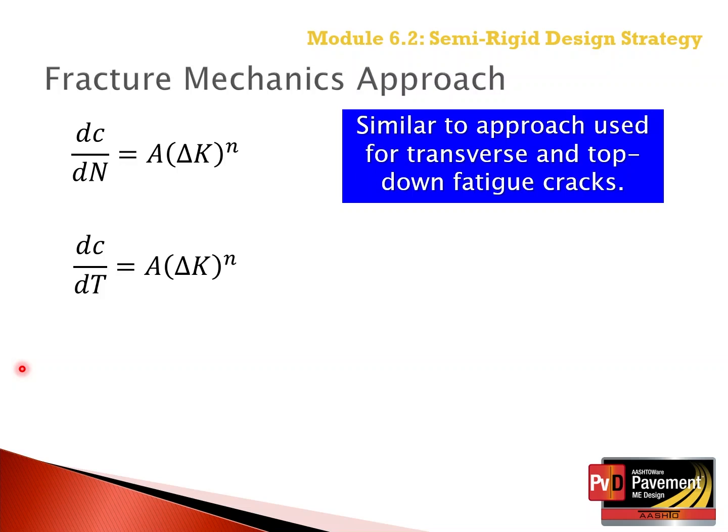In addition, a granular base or subbase was assumed below the chemically stabilized layer in all of the finite element runs to generate the artificial neural networks.